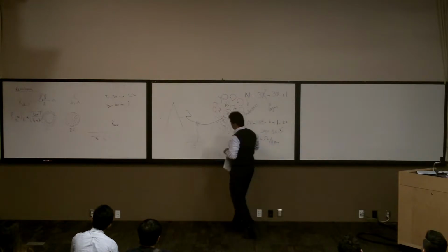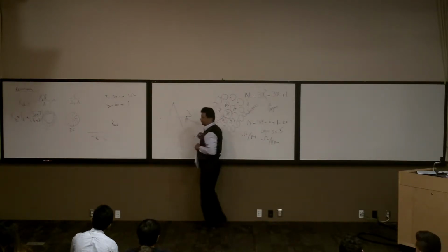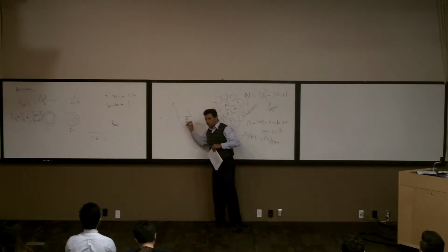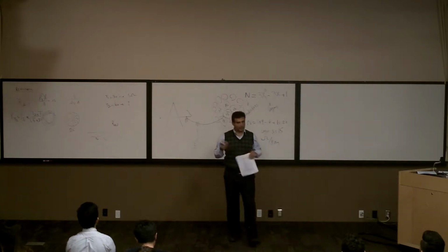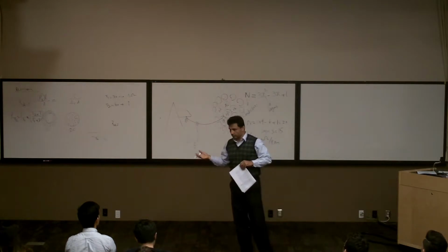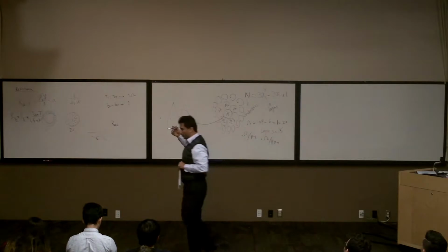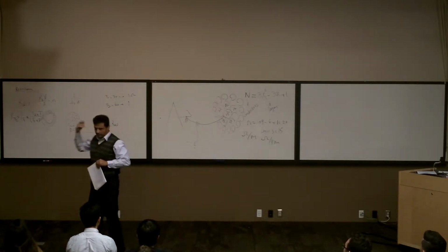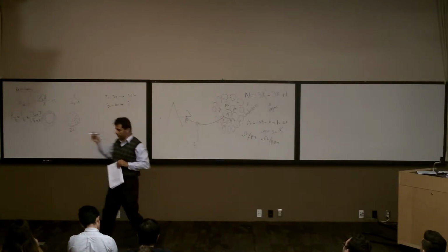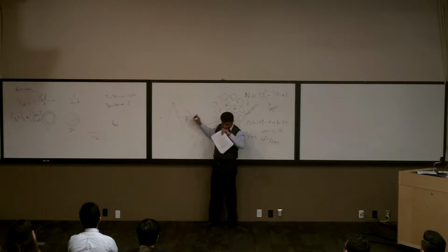This is one. The next thing is, if you look here, there is a system like an insulator. These cables are connected to this. This insulator is not a perfect insulator. They have some leakage current. If they get dirty, it's because of salt. If you're somewhere close to a hot area, next to the ocean or rivers, there's salt in the air. It's going to come on this. Salt is a pretty good conductor, but it's still not very good.